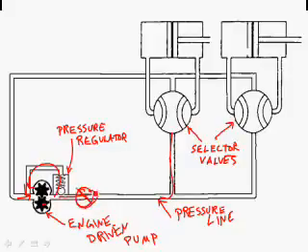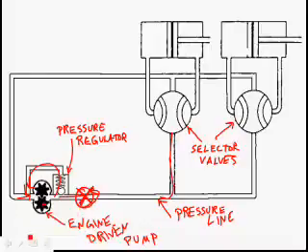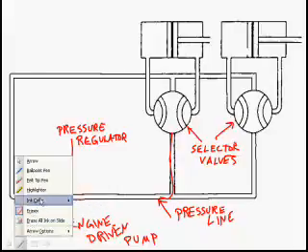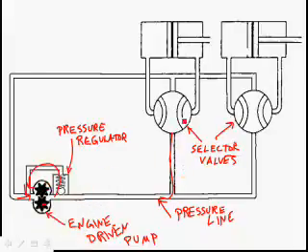Sometimes they put isolation valves in here. You can turn it off right here, so you can isolate the system from the pump, but there's no way to get the pump to stop spinning. Okay, if we rotate this one, let's say we rotate this selector valve to the right, fluid's going to come up in here. It's going to fill this side of the double acting actuator.